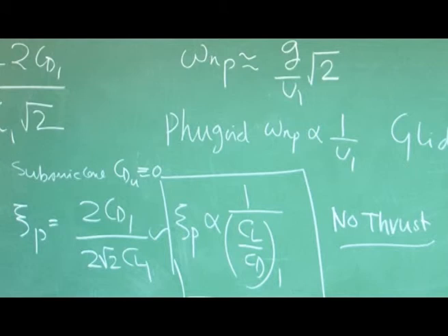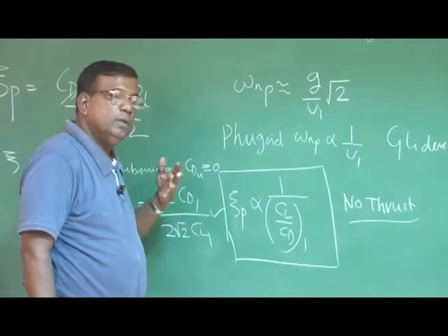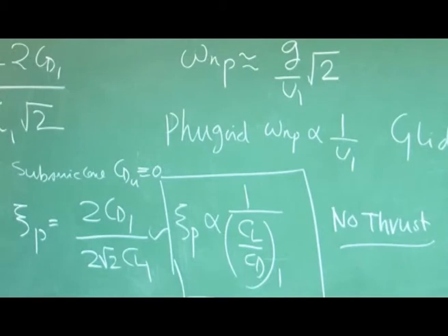So, this was a closer look into Phugoid approximation and short period approximation. We want to avoid using those huge matrices. We found 2 by 2 matrices we will use, and we got some relevant information in short period mode and Phugoid mode through approximations.